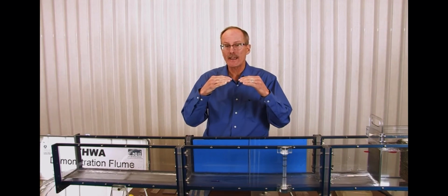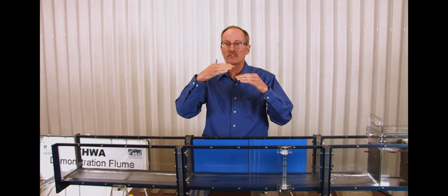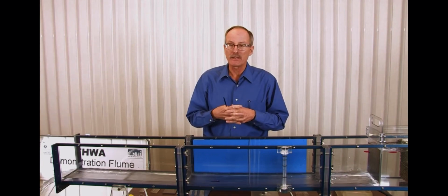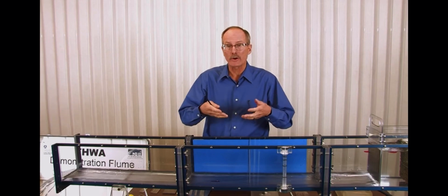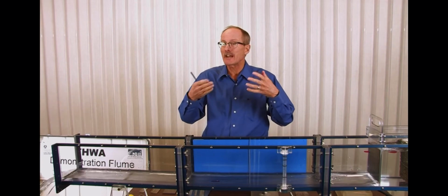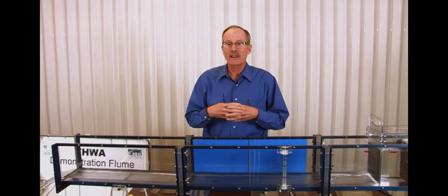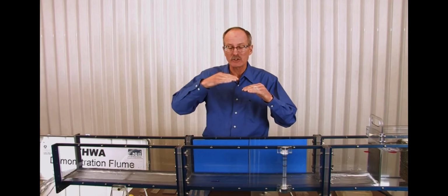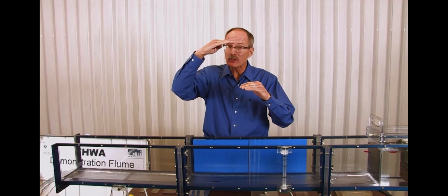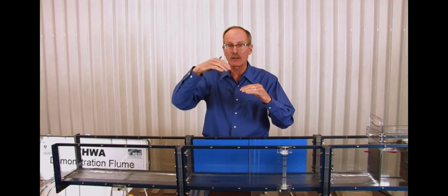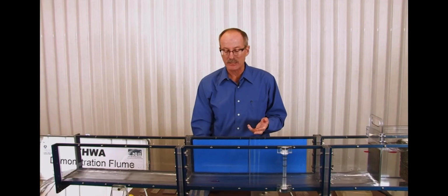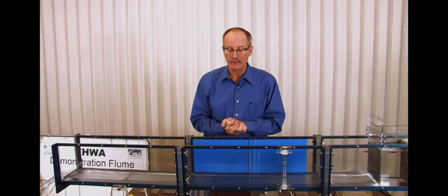That pressure head reflects the rise in, say, a standpipe. So what is a standpipe in application? Well, it'd be our catch basins, water coming up in those. It might be the access hole. It might be the pipes connecting to the catch basin. If we have a conduit under pressure, that HGL will rise up, and if it rises too high, water in fact starts coming out of our storm drain system instead of going in. So the energy equation is how we evaluate that, and in particular, we pay attention to what the hydraulic grade line is doing.